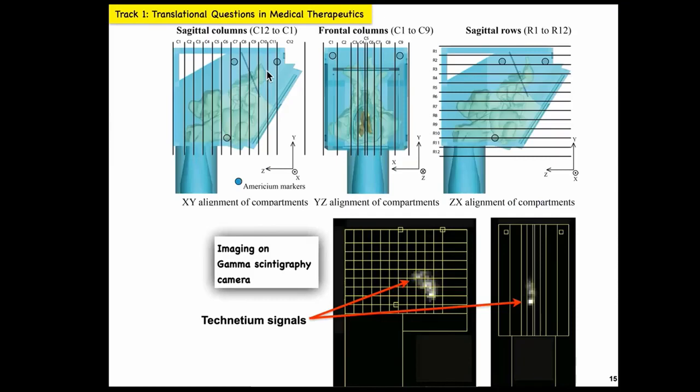However, yes, the kind of time domain that we are trying to simulate, especially if we are thinking about relaxed, steady breathing, in the sense that the person is sitting and breathing at a very low rate, that delta T amount of time, you can assume in all probability that the flow features are going to be steady because it's around 0.2 to 0.3 seconds at most. But of course, if you are trying to simulate on a wider time interval, steady would be too stretched an assumption in that case. Okay. Thank you very much.